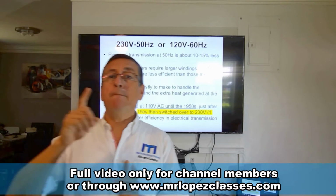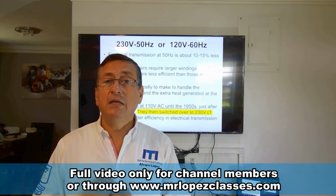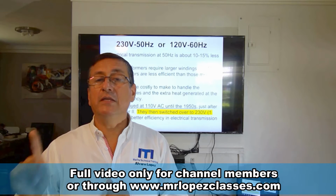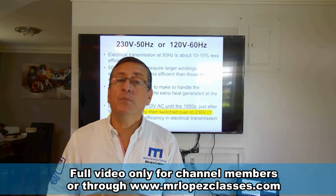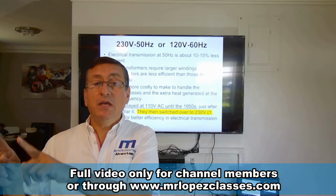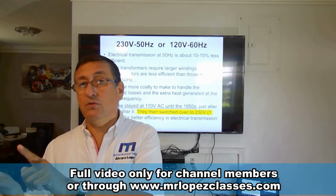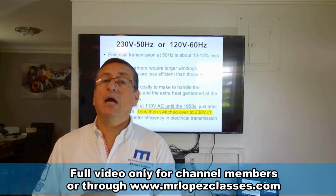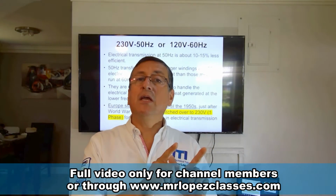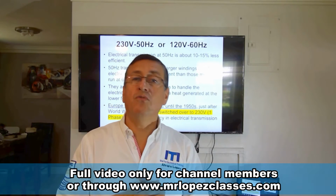In American generators, in order to produce 240 volts, I need double phase. In European generators, in order to produce 230, you need only one phase. Are there European generators double phase? Yes, and the reading in between each phase and each phase is 460: 230 and 230, 460. And the double phase American generators, the reading in between phase and phase is 240.